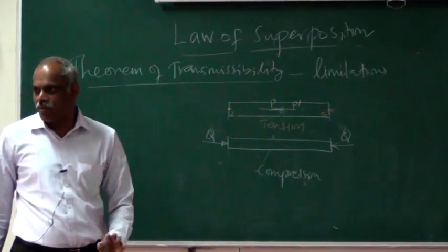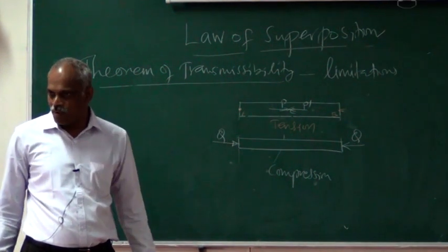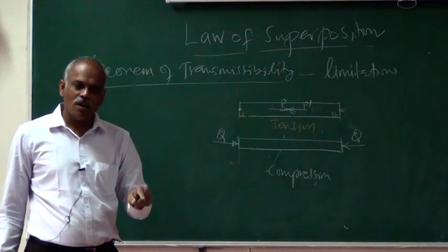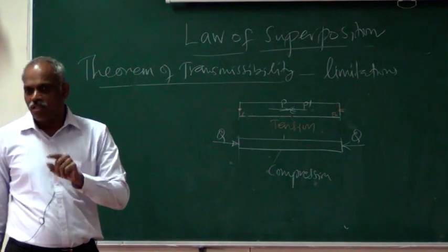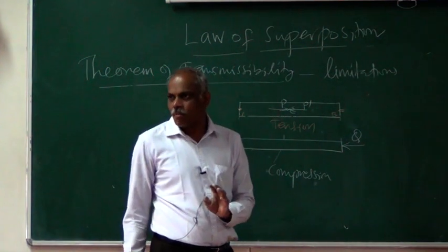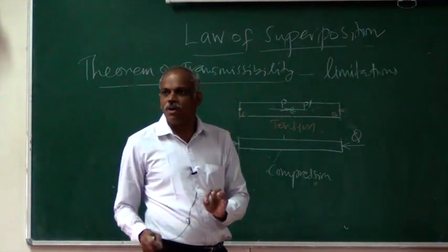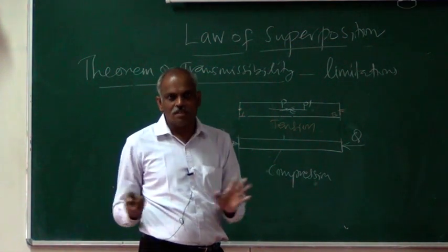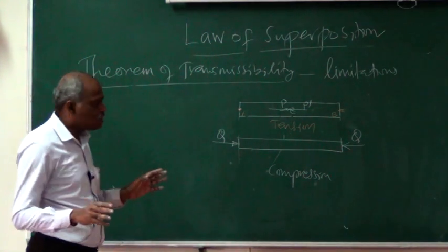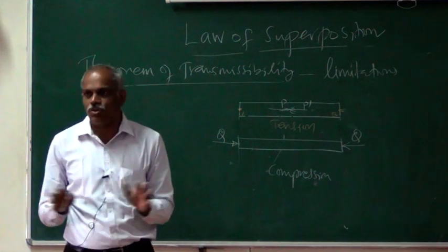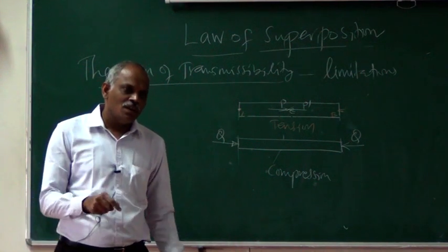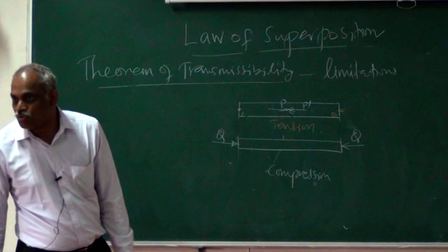So we discussed what the theorem of transmissibility is. We proved the theorem of transmissibility using the law of superposition, and also we have stated the limitation of using it. The theorem of transmissibility cannot be used where you are concerned about the internal stresses or internal forces, so you have to be cautious. As far as statics is concerned, it can be used without any botheration, because the system will still be in equilibrium. But when it comes to strength of materials or other subjects where you are bothered about internal stresses, you cannot use it. That is the limitation.